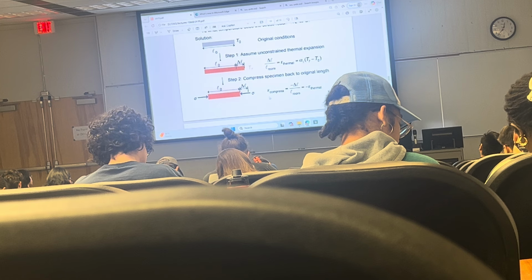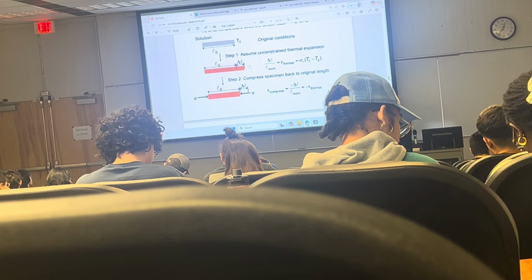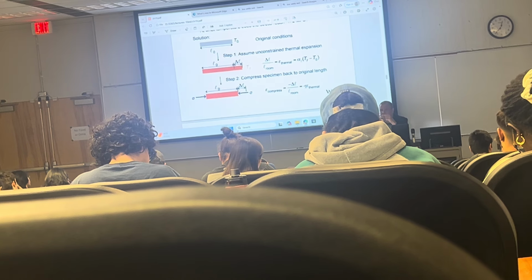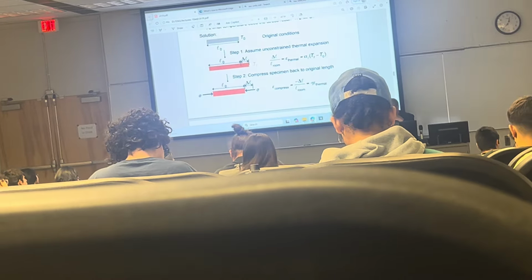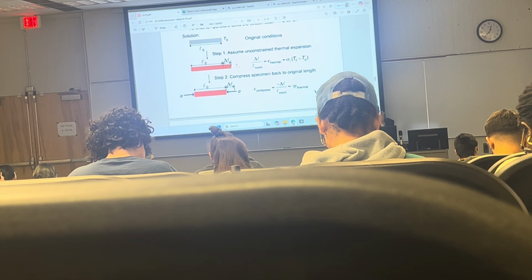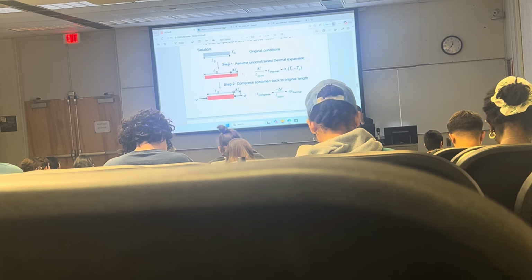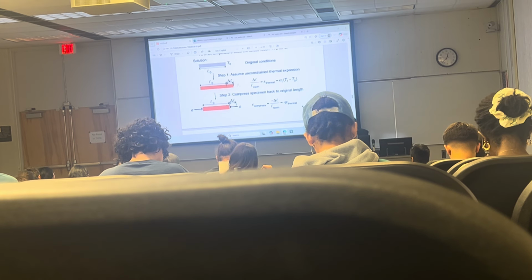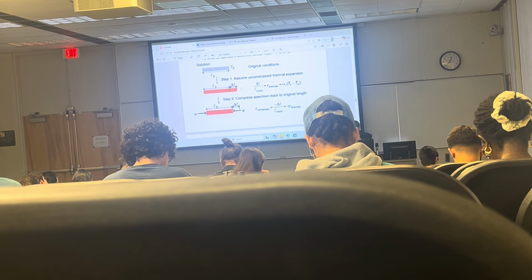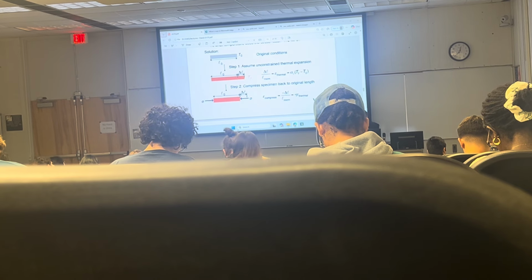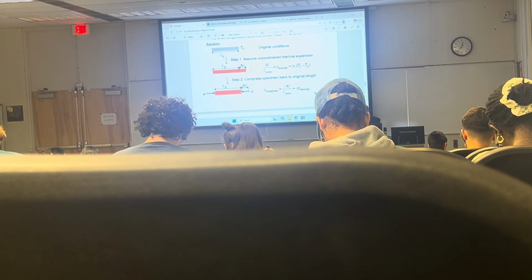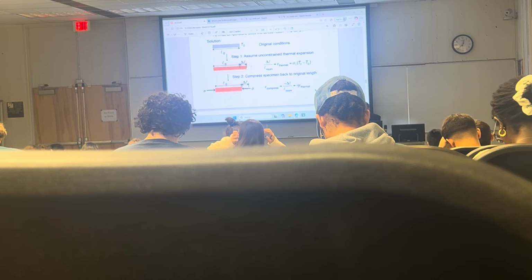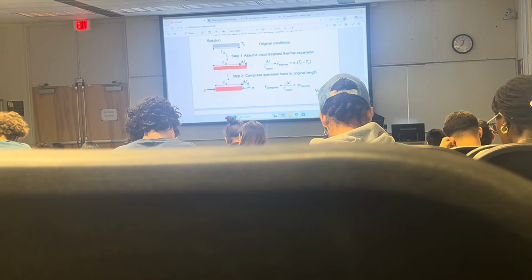So we can write that the compressive strain is equal to minus delta L over L, and that's equal to minus thermal strain. Okay, they work against each other. So what the material wants to do when it is expanding, becomes longer, right? So that part, even though it is heated and it expands, we treat it as tension. I want you to follow the logic. So we treat it as tension, it expanded, and then I come back and push it back to its original dimensions between the two steel plates.